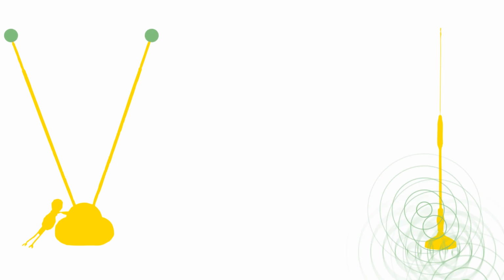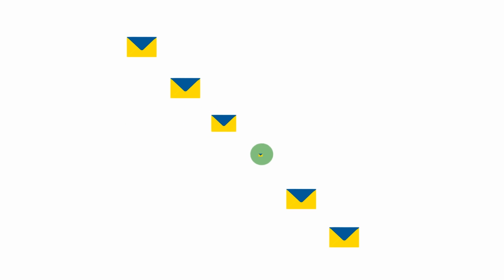On the receiver, data is continuously acquired whilst the transmission process is enabled. To locate each received packet, the continuous data is filtered for noise and DC offset and then chopped into processable chunks. Each chunk is then converted back into binary representation through the demodulation process.